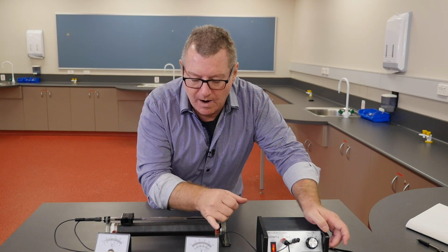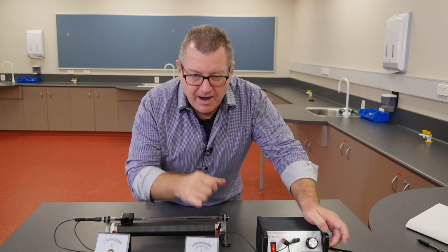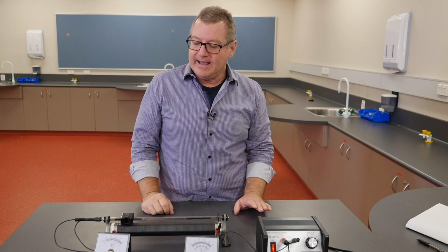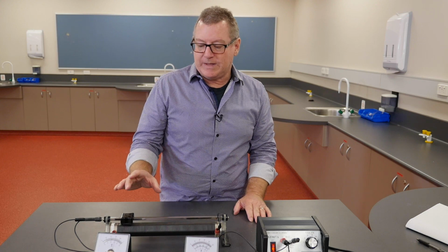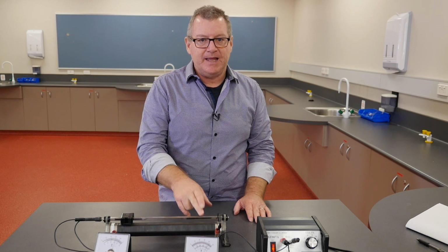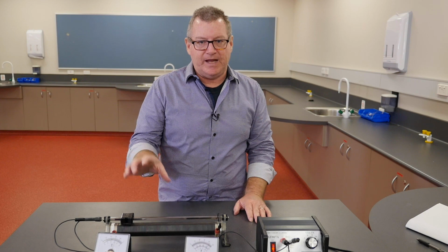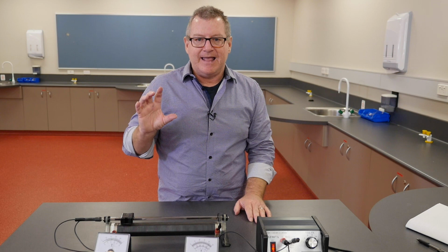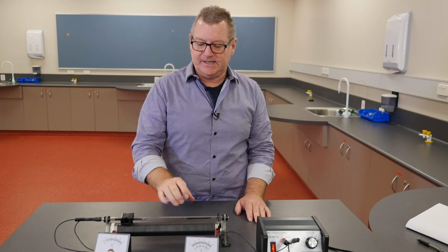We could also move to a higher scale and do some more measurements, but those 3 will be enough because we are already assuming that it's a linear graph, and 3 points is enough to establish a straight line. So that will give us a sense. We could, if we wanted to, do that for multiple values of the resistance as well and measure them. But for the purposes of this, we will get multiple data points for each of the 2, 4, and 6 volts, and then calculate and average those and graph V versus I to find the value of R for this resistor.